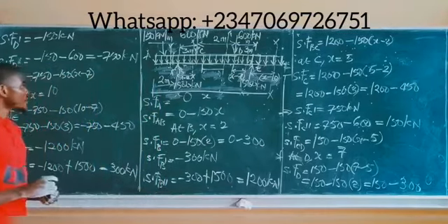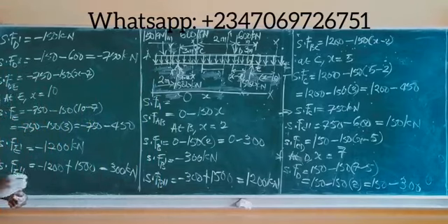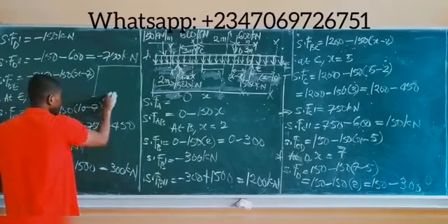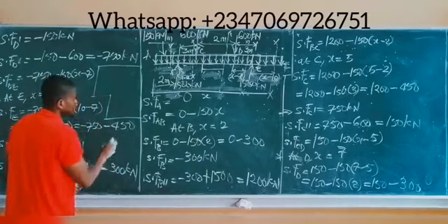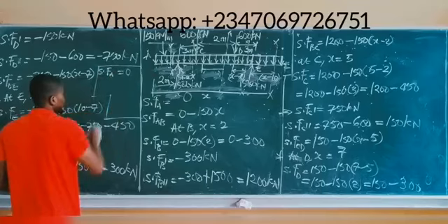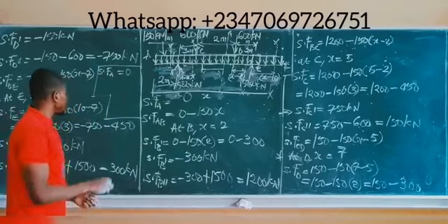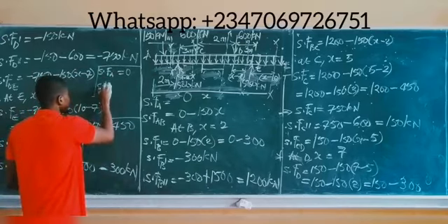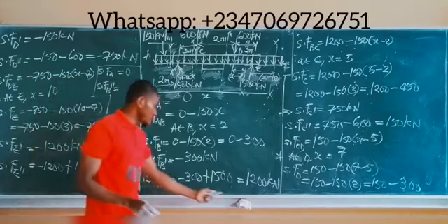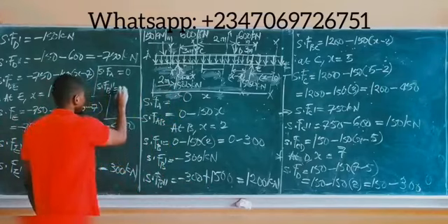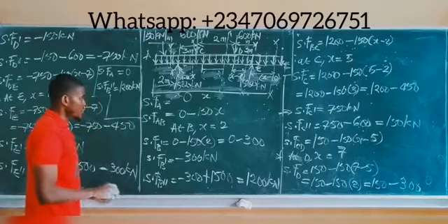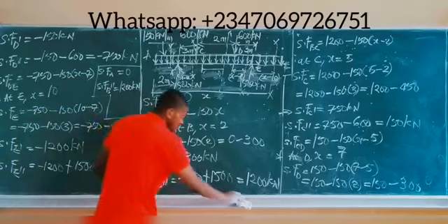Okay, so I will actually need the shear force values. Let me just pick it up somewhere here so I can make space for myself on the board. Shear force A actually gives us 0. And shear force B prime, which is the shear force at point B, gives us 1,200 kilonewtons. Alright, so I can wipe that and make space for myself on the board.